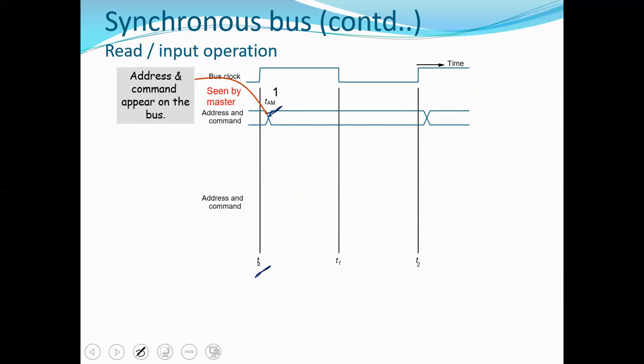Why is this delay? This delay is because some time was taken for the complete address to be in the bus. At that instant itself, it is not visible in the bus. Fine. There is some time taken for the movement of data in the bus, for the filling of the whole address in the bus. So that time taken is the small time which is shown.